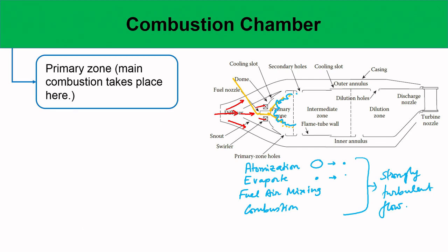It involves kinetics, it involves oxidation mechanisms, and you need to know this whole process of fuel air mixing and how it happens, which is governed through the governing equations. If it is a non-premix flame, then locally you can use the flamelet approximation that you have seen, which involves the solution from the counterflow flame. If it is a turbulent premix flame, in some places you can use the analysis of the 1D premix flame that you have seen and apply the stretch concepts to derive a more generalized function of flame speed. And if it is a premix flame, you can use the G equation to find out how it will evolve.